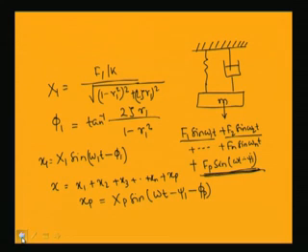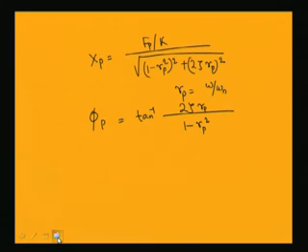So, in this way when we have a number of forces acting on the system, then we can find the response of the system by finding the response of individual forces and then adding these responses. So, this is known as the superposition principle. So, using the superposition principle, we can find the response when a number of forces are acting on the system.